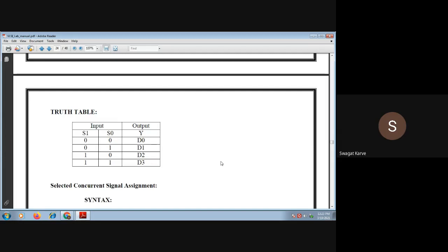Depending upon the application, you can have 4 is to 1, 8 is to 1, or 16 is to 1 multiplexer. What changes do you need to make? The number of select pin combinations will increase. If you use an 8 is to 1 multiplexer, how many select pin combinations are possible? 8 combinations, and for that you need 3 select pins.